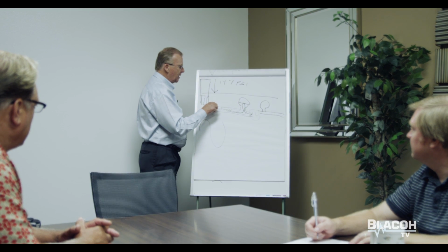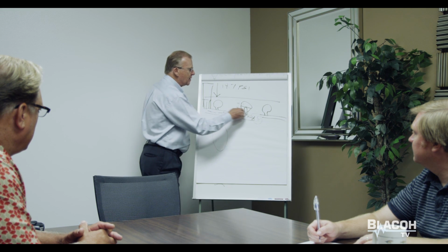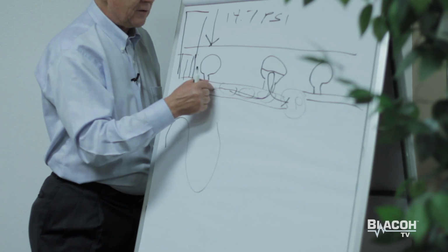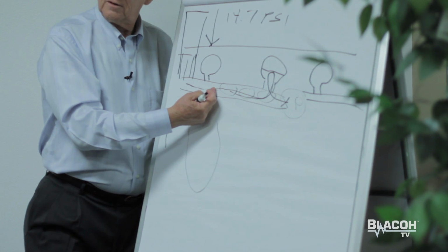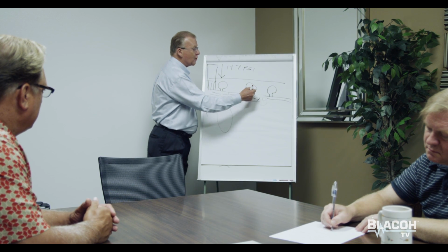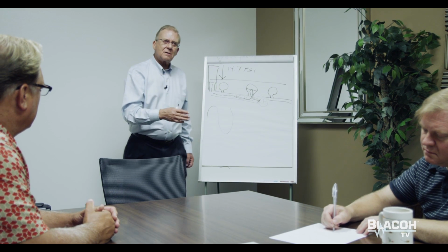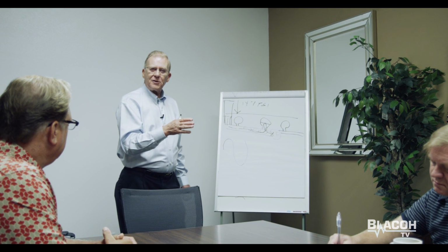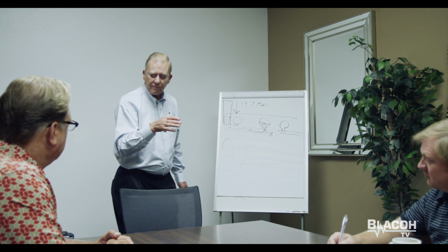So if we move the dampener here, for example, everything from here on is going to have this acceleration problem because the valve is opening and closing and affecting this length of pipe flow. So the inlet stabilizer or the dampener needs to be installed as closely as possible to what is causing this acceleration head loss or positive pressure, okay?